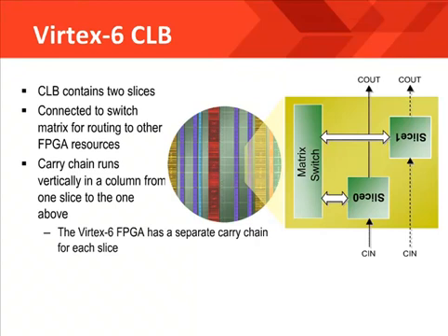The LUTs and registers are grouped into slices, which also have other dedicated resources. Besides LUTs and registers, slices also have carry logic resources, which are designed to implement arithmetic logic functions with high speed performance due to the dedicated carry chain, which runs vertically in columns from one slice to the next.